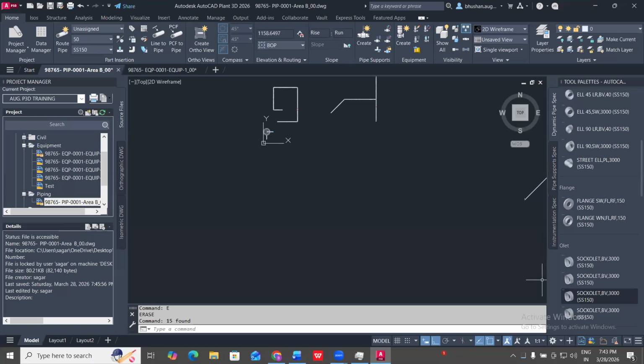Let's move to a more advanced part in these bends, which is cutback elbows, right? So cutback elbows and roll elbows, these are used when you are routing a pipe on a slope, or on a different angle. Like you want to take your elbow angle differently. It will not be a standard.